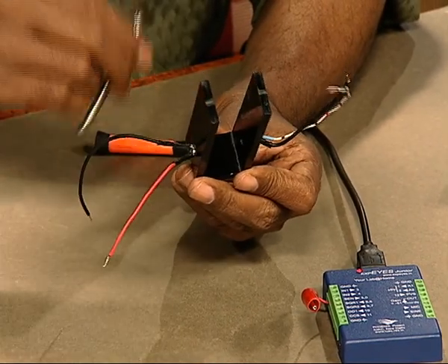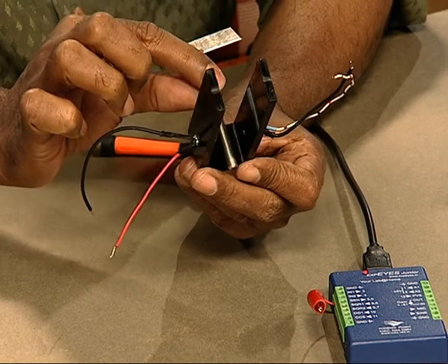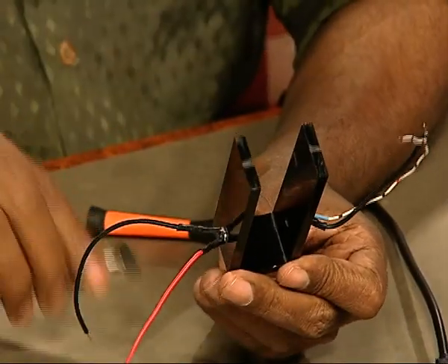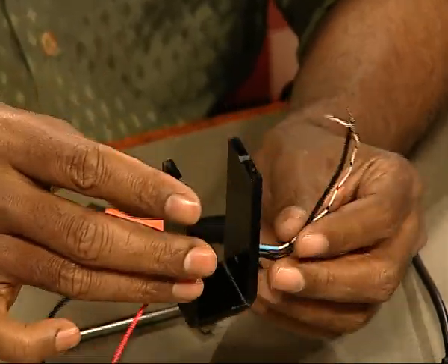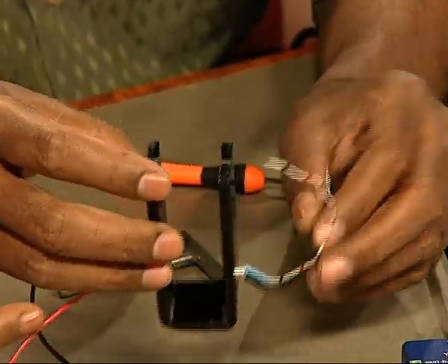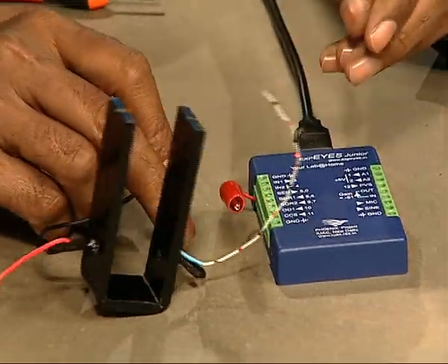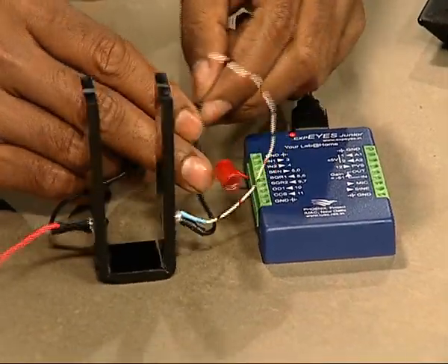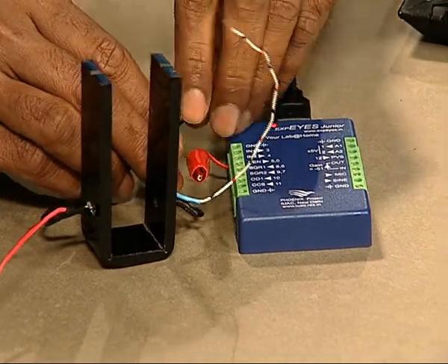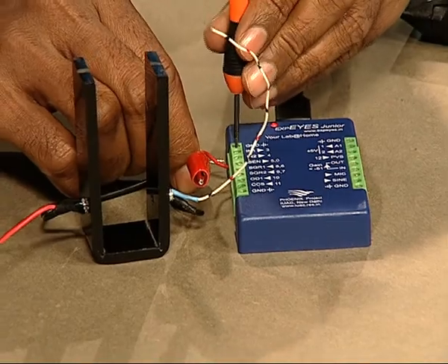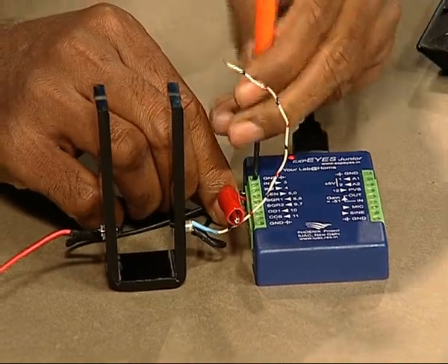When the pendulum is oscillating, whenever it intercepts the light, the phototransistor can sense it and generate a voltage transition. So, that is what we will try to utilize. Let us make the connections: both of these grounds, the LED as well as the phototransistor emitter, are connected to ground.